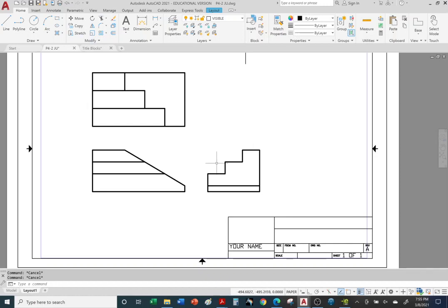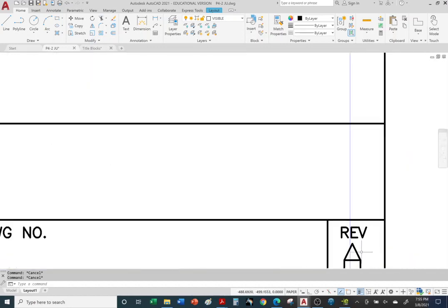So then, since you already released this drawing, it went through the process of names, signatures, approval. It went through the document control process. And this was already quoted. And the drawing was finalized and approved. You got to stop the machine shop and call them and say, hey, you know what? We need to make a change. Have you guys started machining? Like, no, we haven't started machining yet. Okay, we're going to send you a new drawing. The part is taller. So now you have to change the revision to a B.